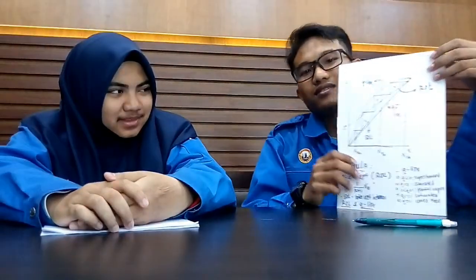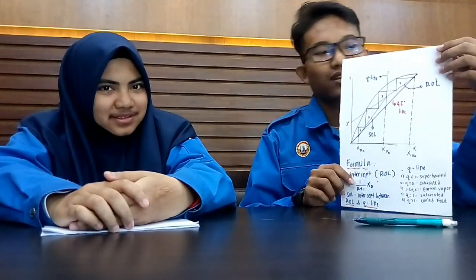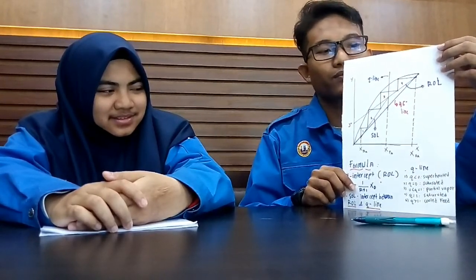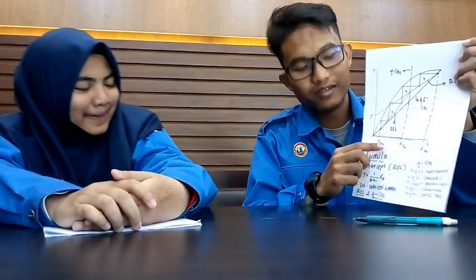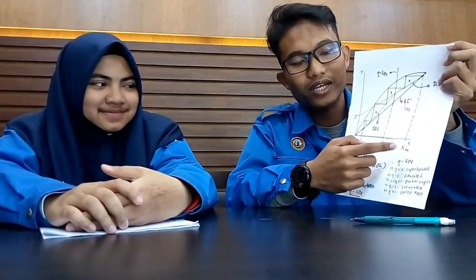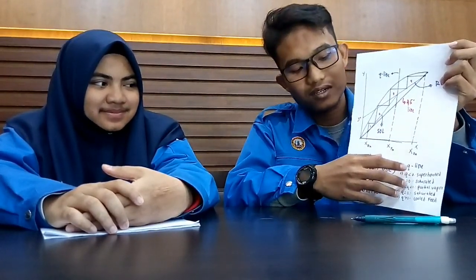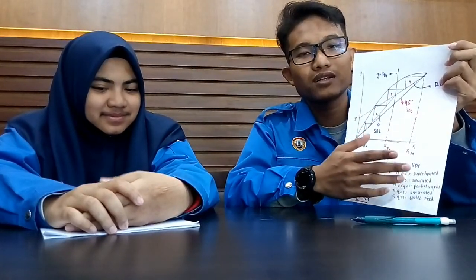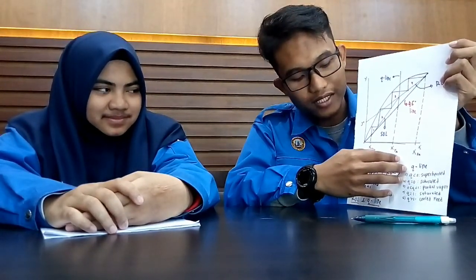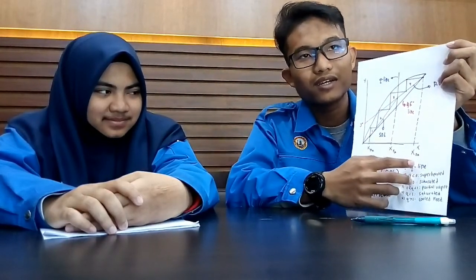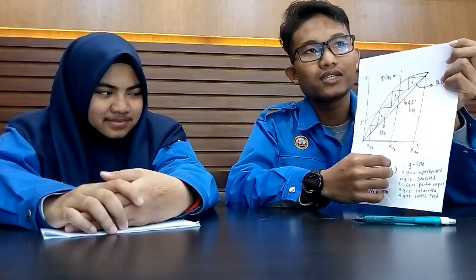In conclusion for question 2, distillation part, McCabe-Thiele is the mathematical graphical method used to determine the number of stages. This is the overall picture for the McCabe-Thiele stage, where there are three main important points, which are xB, xF, and xD. These three values we get from the material balance. Before we proceed with McCabe-Thiele, we must ensure that xD, xF, and xB are in mole percentage. If they are in weight percentage, we must convert them into mole percentage.